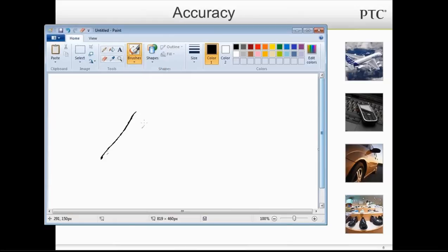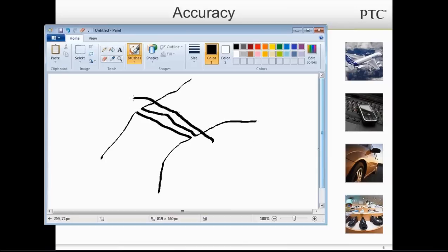If I take a surface, something like this, and then I want to connect it and merge it on to a surface, something like this, accuracy is what ProEngineer uses to calculate how close these two surfaces are actually touching. And where it comes into very, very big play is that I might be able to merge these two surfaces together, but because of the value of my accuracy, there still might be gaps. So the merge will go, but there will be gaps.